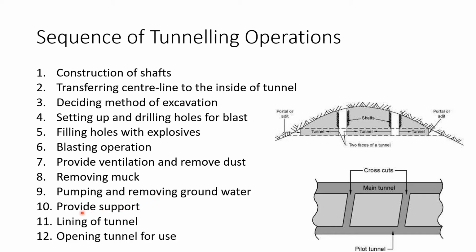Then we need to provide adequate support inside this tunnel. Once the support systems are provided, we have to line the inside of the tunnel, the lining of the tunnel. Once it is completed, we can open the channel for use. So these are the sequence of tunneling operations that are carried out for tunneling in hard rock.